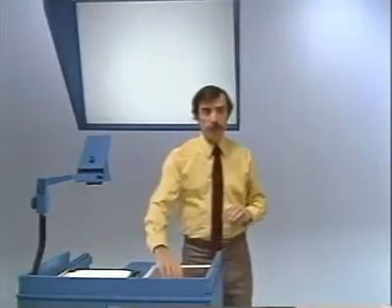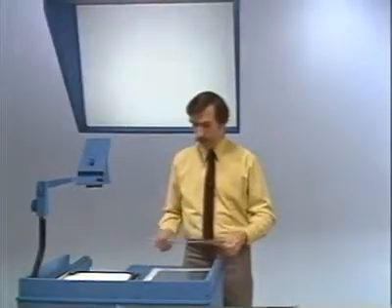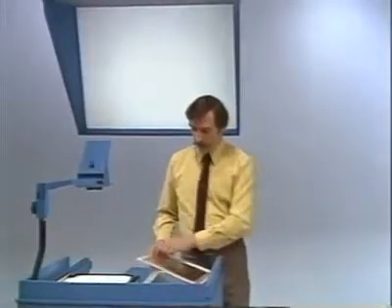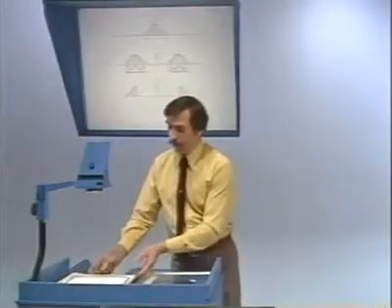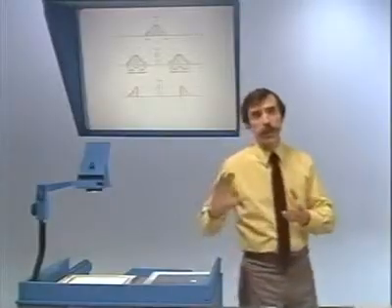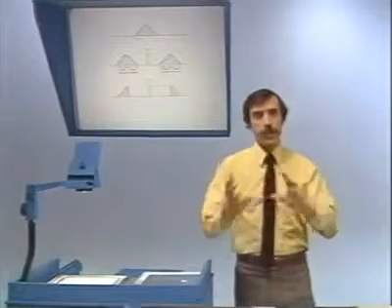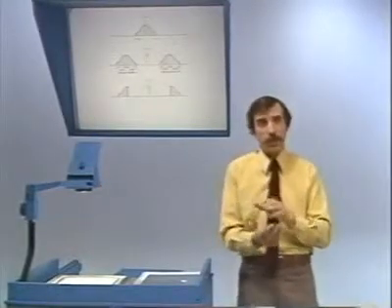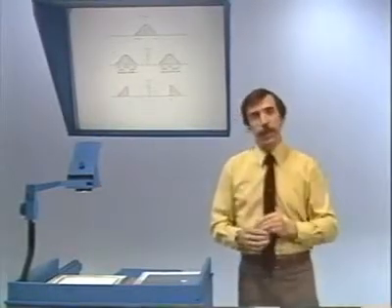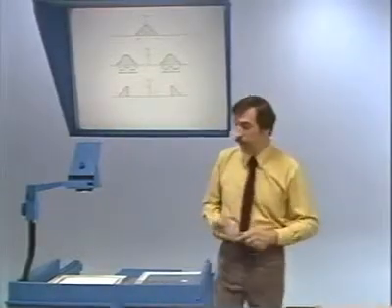Now, in the asynchronous system, as we've indicated, there's one source of inefficiency, which is this injection of the carrier. There also is a somewhat different issue related to inefficiency in sinusoidal amplitude modulation, and it's an inefficiency that is separate from the issue of synchronous versus asynchronous systems. In other words, it's not associated with the injection of the carrier. It's a very different issue.